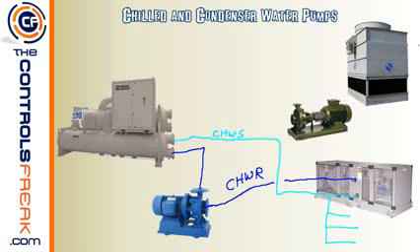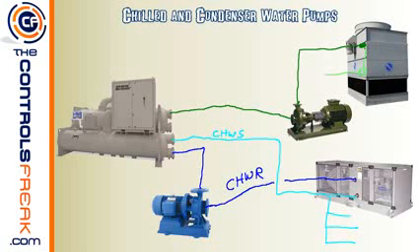On the condenser water side, you'll have the hot water coming out of the chiller. We're going to draw this one as if it's coming into the pump, and it's going to come out of the pump and into the top of the tower right here. So that hot water is going to come across, get cooled down with the fan on, back into the basin, and from the basin it's going to get sucked back out and come back into the chiller right there.